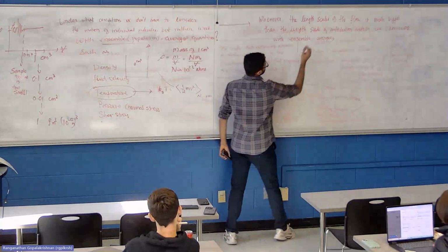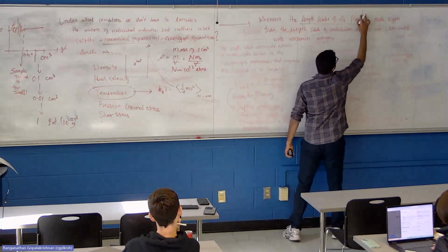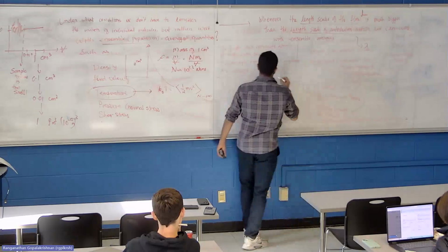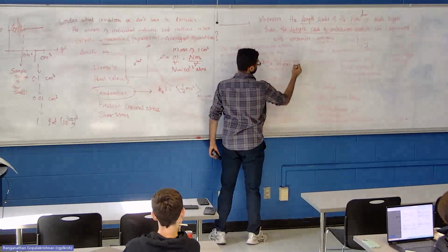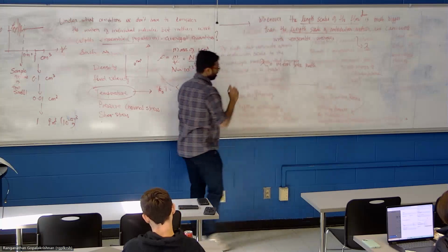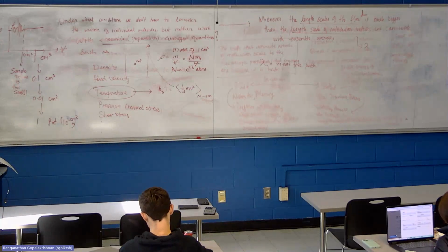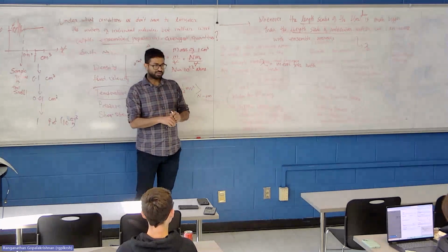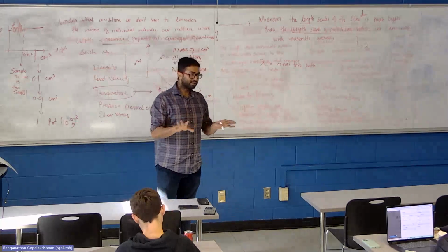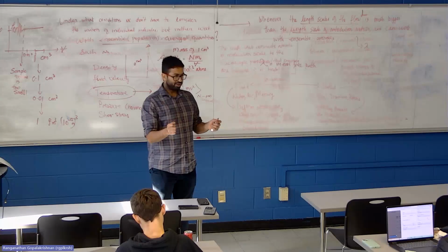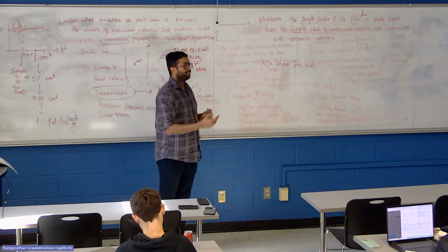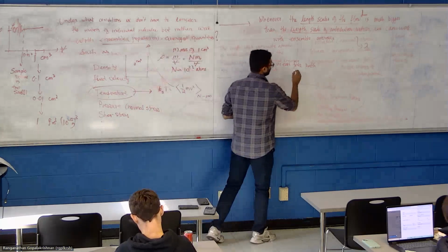If we denote the length scale of the flow as L, and the length scale of molecular motion we'll denote as lambda, where lambda is sometimes called the mean free path. What is mean free path? Suppose we are about 18 of us here. We all start walking around randomly in this room. Okay, we'll keep bumping into each other. If I define the distance, how far can I travel before I bump into someone else? That distance, mean free path.